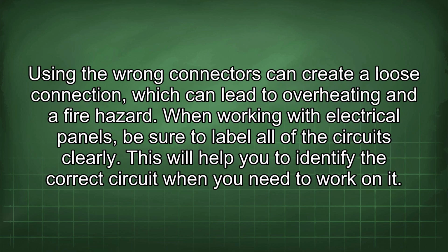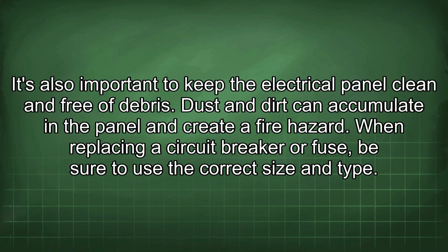Using the wrong connectors can create a loose connection, which can lead to overheating and a fire hazard. When working with electrical panels, be sure to label all of the circuits clearly. This will help you to identify the correct circuit when you need to work on it. It's also important to keep the electrical panel clean and free of debris. Dust and dirt can accumulate in the panel and create a fire hazard.